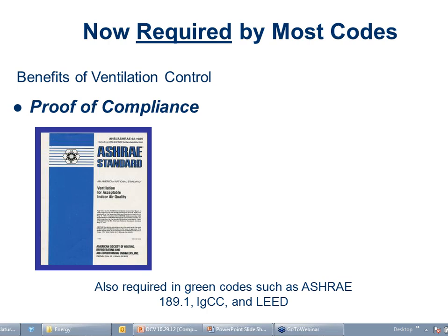Because if you remember, I'm not going to modulate any dampers open more than they would have already modulated. I'm going to modulate them down less when less people show up. So I still size the air handler and the reheat coils and everything the same for the exact same capacity. The only difference is if people don't show up, I'm going to modulate the damper down a little bit and provide them less ventilation air, which means I'll use less reheat.